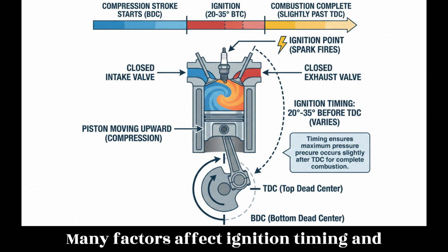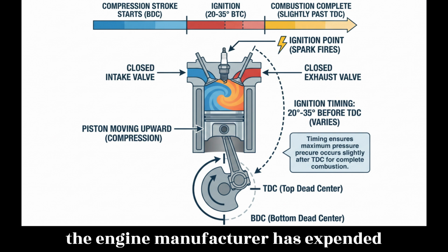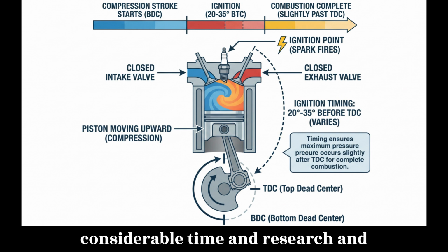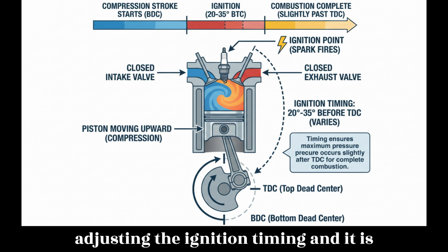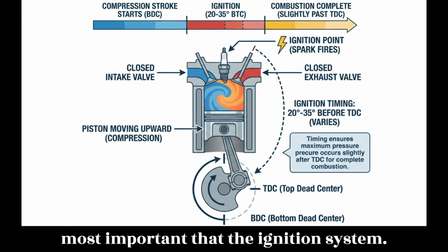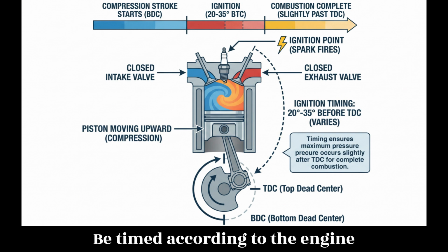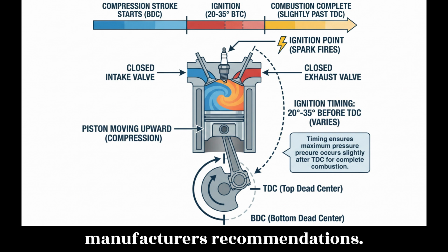Many factors affect ignition timing, and the engine manufacturer has expended considerable time and research and testing to determine the best setting. All engines incorporate devices for adjusting the ignition timing, and it is most important that the ignition system be timed according to the engine manufacturer's recommendations.